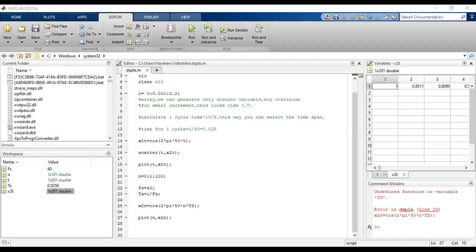discrete time signal. So we have sample numbers 0, 1, 2, 3, 4, maybe negative samples also, like -2, and we have different values like this. You can mark these values using the scatter command.